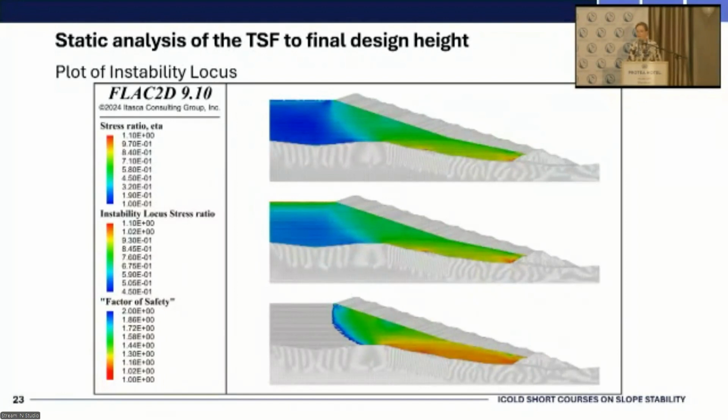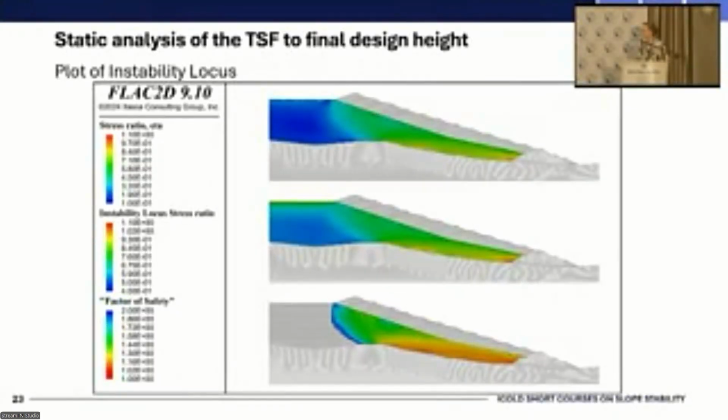Within the core of the facility, we can see factors of safety exceeding a value of 2, and then closer towards the toe of the facility and at the base of that potentially liquefiable overflow, we've got factors of safety that are quite a lot lower than that. So if undrained conditions were to be induced, those would be the levels of stability of those elements within the model.